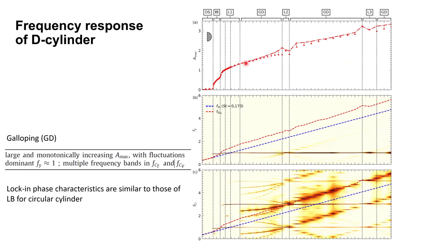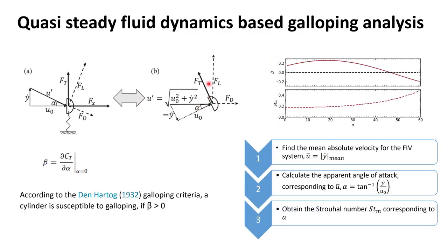Now, once it starts to gallop and has fluctuations in amplitude and also in frequencies, we can see what its dominating frequencies are. Ideally, the dominating frequency should be close to the fluid flow frequency, which is this curve. But what we are seeing is that the frequency is actually closer to another frequency, which is modified. Based on this movement, which is moving faster, we can also modify its Strouhal frequency, which means that had it been stationary, it would feel more forcing and the Strouhal frequency.